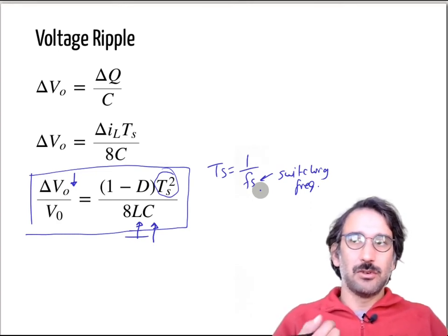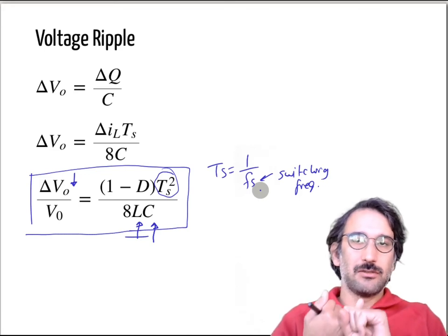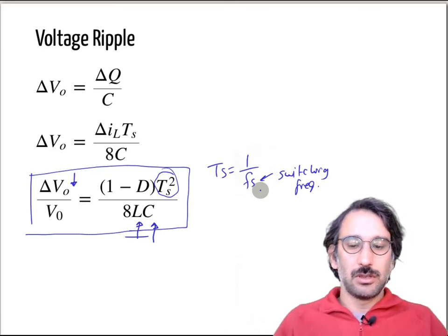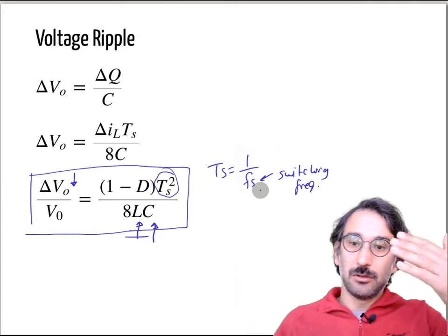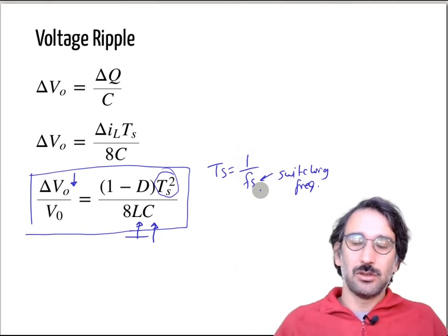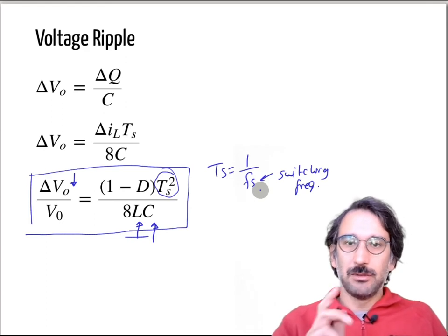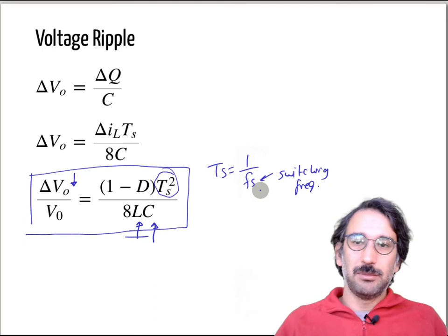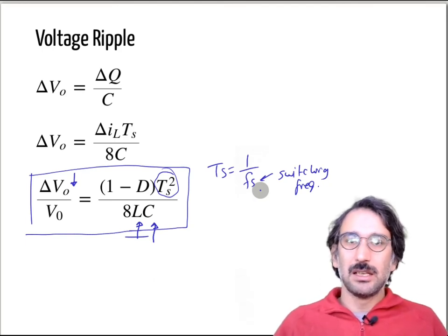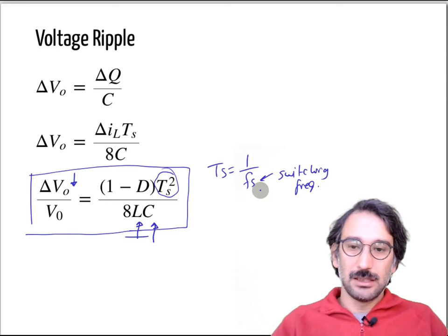First, increasing switching frequency will increase your switching losses, both in your MOSFET or main switch and in your diode. Secondly, even if you can thermally cool it down, there may be problems with the turn on and turn off times, and there's a maximum switching frequency limit that you can achieve with that device.